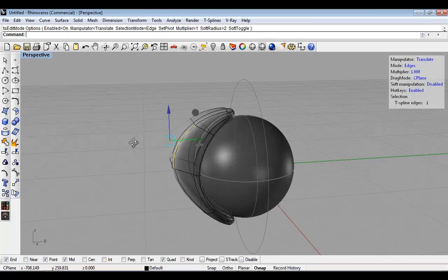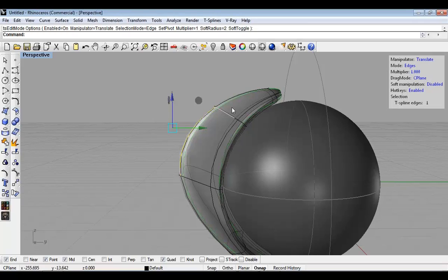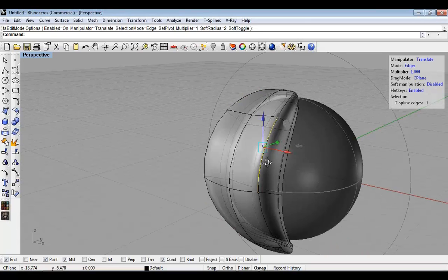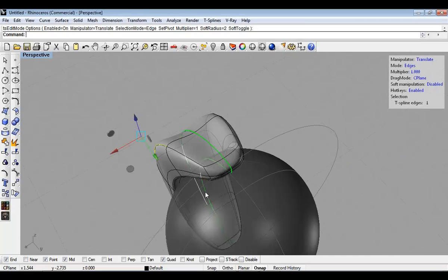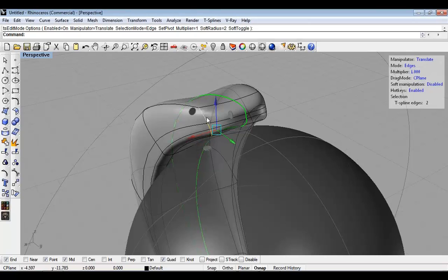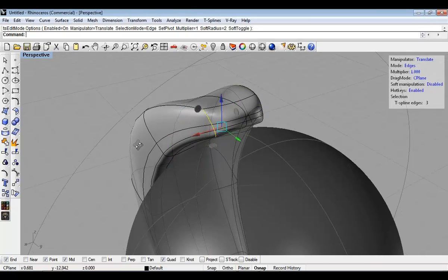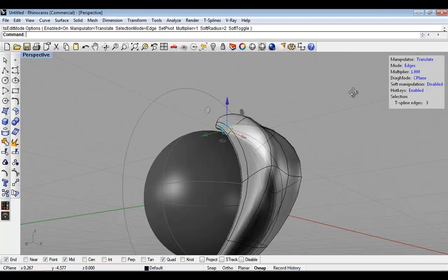Okay, so that's round about the face area I need, and the jewelers watching this will know that I'm leaving enough thickness here to give me about 0.9 of a wall on the inside afterwards, which is just thick enough to set the stones in. Now, I think that my snake's nose needs to be a little bit narrower than this, so I'm going to just grab these sections. Okay, and you'll see what I mean. I think that looks more snakish and less lizardish.